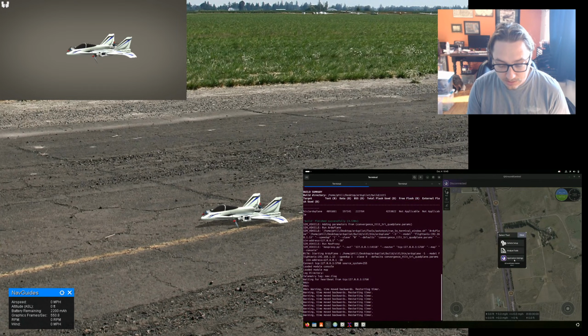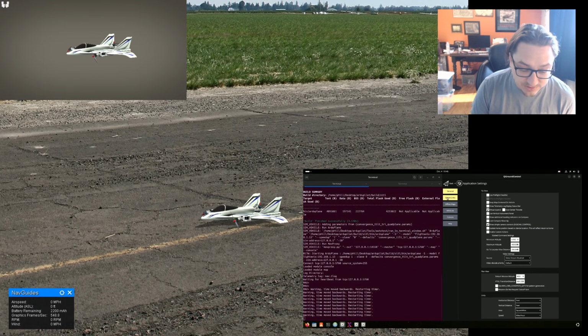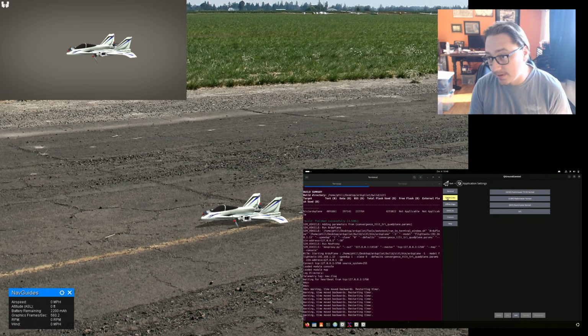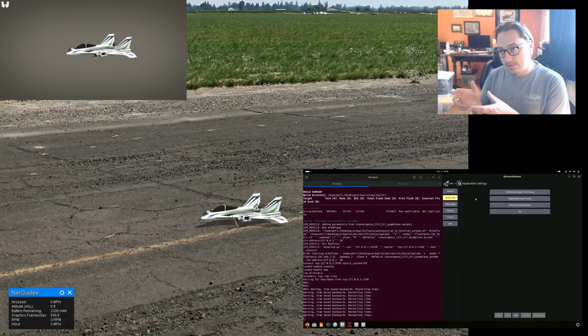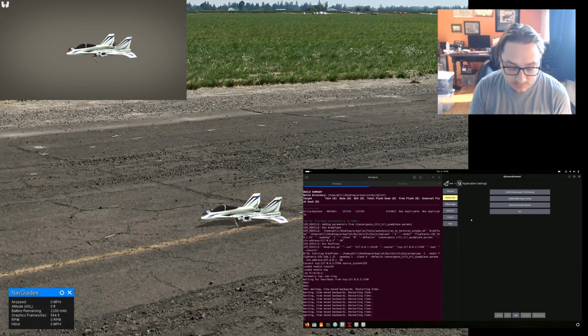We're good. So now I'm going to get our laptop ground control software connected to the drone. In this case, they do happen to be on the same machine, but once we move to a physical drone, the laptop would connect through the controller handset and send commands to the drone through that telemetry radio, and also receive telemetry back, so we can track it.